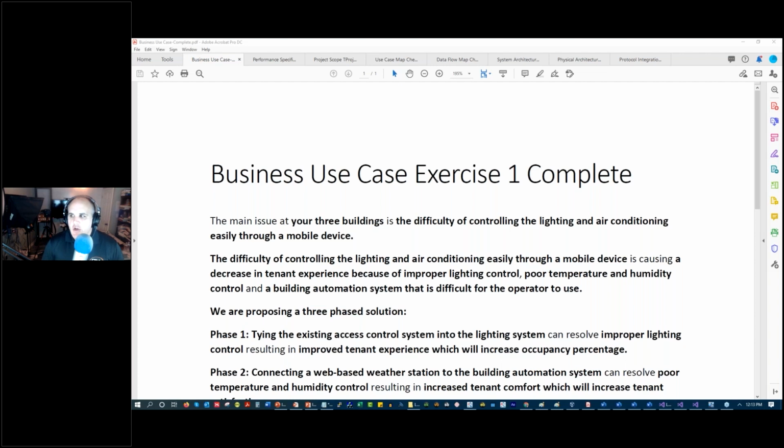And then from there, you're going to get into some details, right? You're going to say, well, maybe we want to add on this room, et cetera. And so that's kind of the detail phase. And then you get to the actual construction phase, construction document phase, which is CDs, where these are very specific details on how it's going to be built. So you go from saying, I want a 2-floor house with an air conditioning unit, to, I want the floors to be laid out like this, to, hey, this is exactly the size of posts we're going to use. Like, we're going to use 2x8s instead of 2x6s, etc. It gets more detailed as the project development goes on.